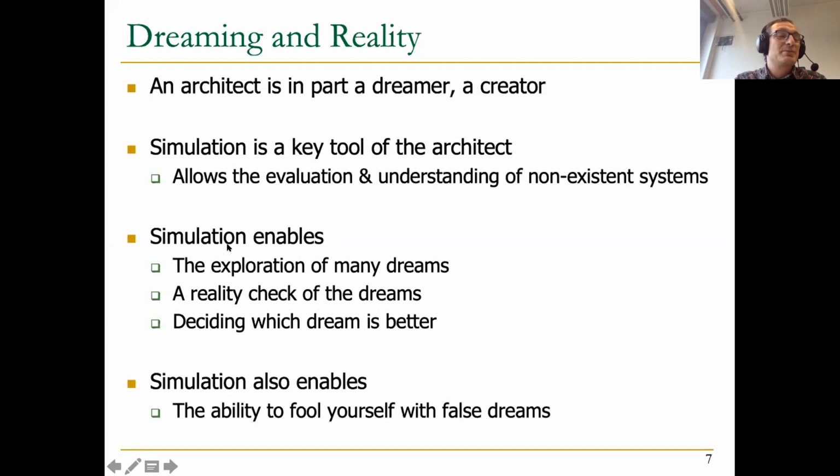So one good thing about simulation is sometimes you do simulation. So we'll talk about different reasons why you do simulation also. But sometimes you do simulation to get a sense of what is the big picture? Meaning, should I do in-order execution or out-of-order execution? In that case, as long as a simulator is relatively accurate, relatively meaning as long as it's accurate in its single bit, meaning whether out-of-order execution is better or in-order execution is better, and maybe some confidence level also, then you may be okay, right? But again, life is usually not that black and white as an architect.